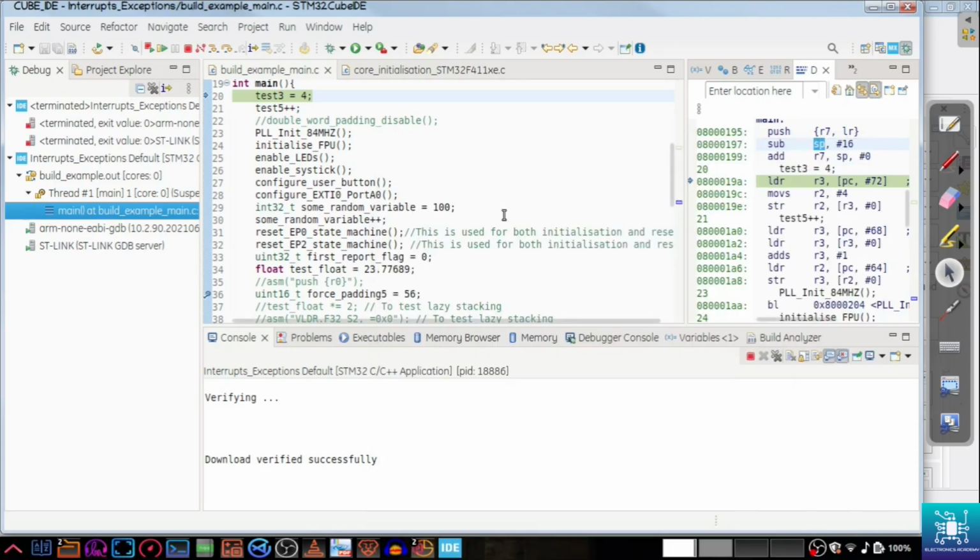But had the stack pointer prior to the main, that is, in the startup, from where the main was called, not been double word aligned, then if you add 16 to that, this will also not be double word aligned. So if, say, your pre-main stack pointer is not double word aligned, say it ends with something like 0C, okay, C is not double word aligned.